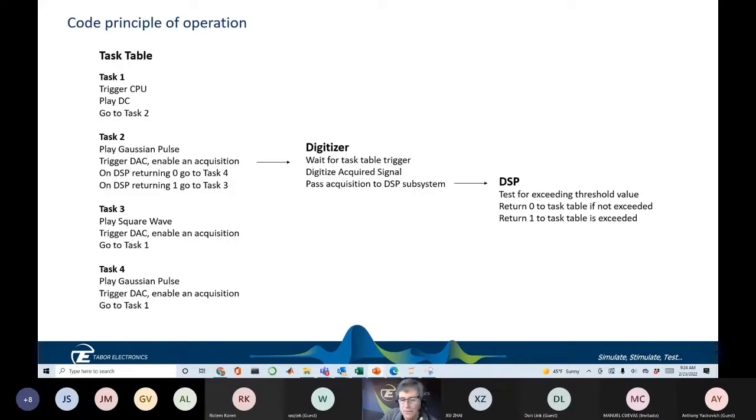So we load all these commands in using the SCPI language into the FPGA, and then it's basically hard-coded into the FPGA, waiting for you to kick off the whole system. After this, no other user intervention is required, although we can pull waveforms out at any time or pull header data out, such as at what time we digitized some stuff, length of waveforms we digitized, etc.